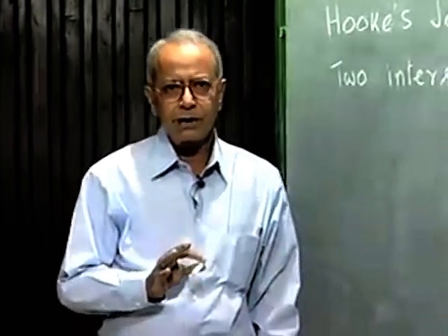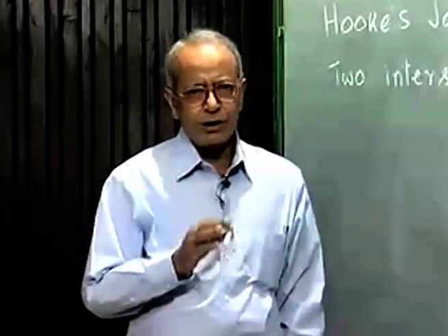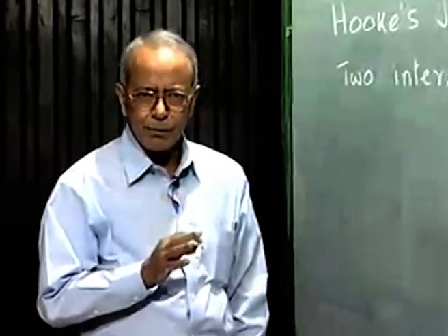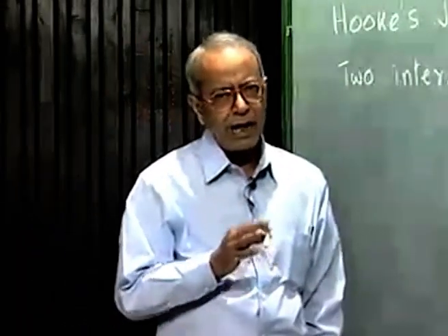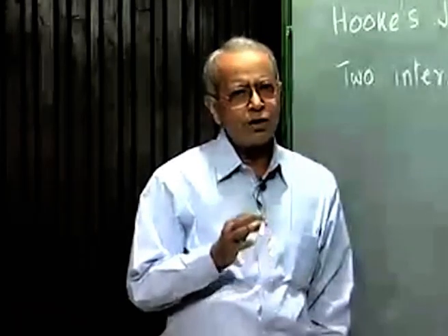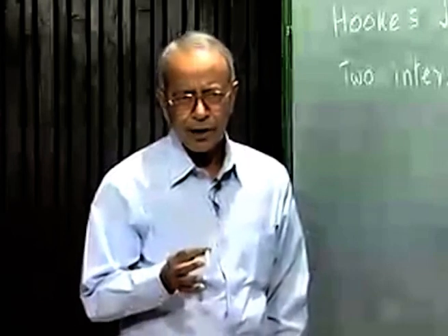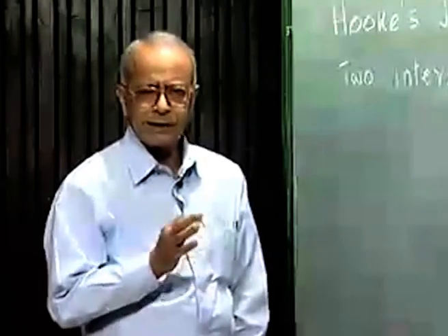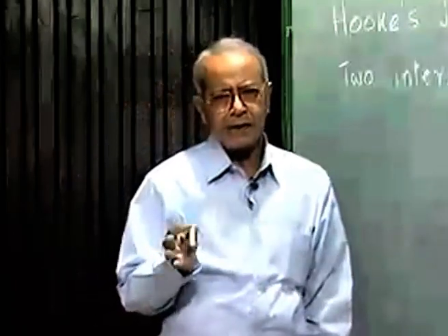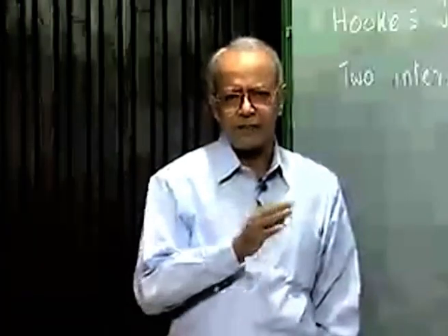Let me now summarize what we have discussed today. We started our discussion with a simple steering mechanism called the Ackermann steering mechanism, which is nothing but a simple 4R planar linkage, a symmetrical linkage such that identical turn can take place for the right hand turn and left hand turn.